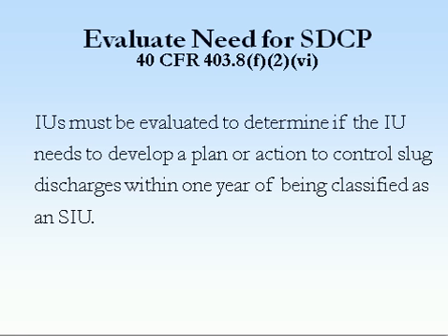And evaluating the need for a slug discharge control plan is different than determining if they have one. A lot of folks seem to think that asking the industry if they have one or if they don't have one is enough for the evaluation, but you actually have to evaluate whether or not that industry, in your opinion as the control authority, has the potential to slug you.